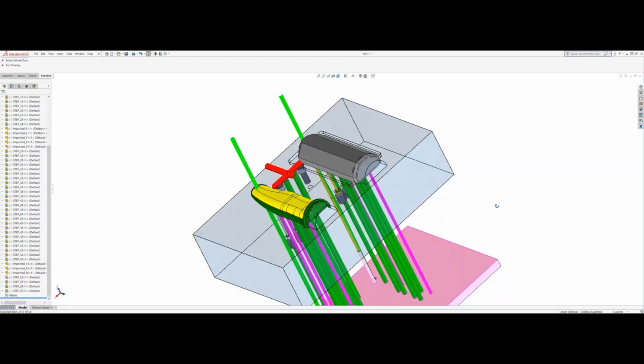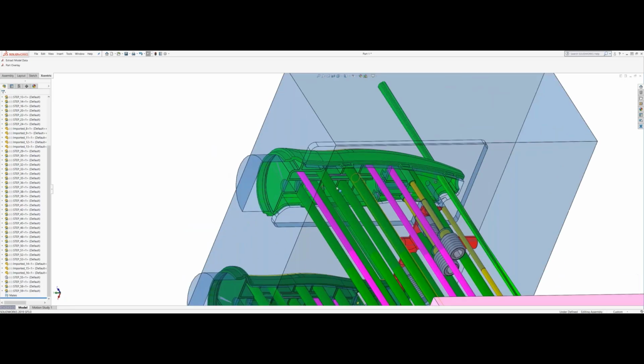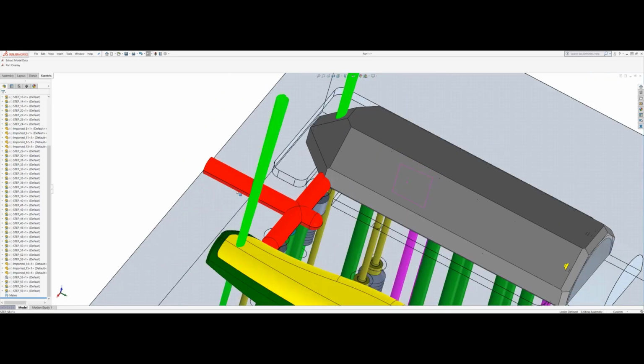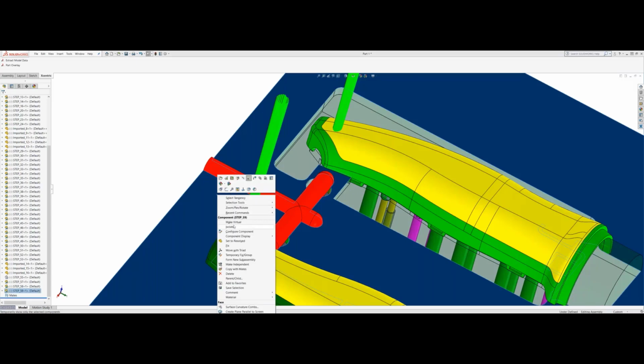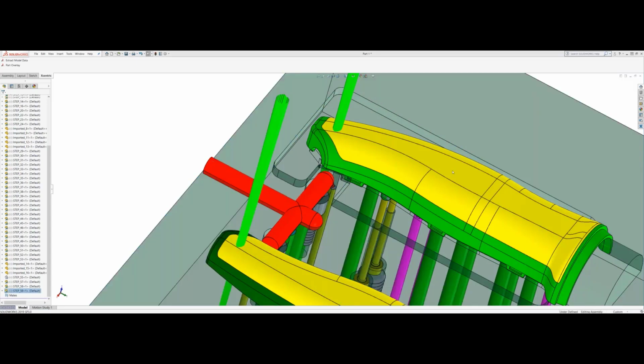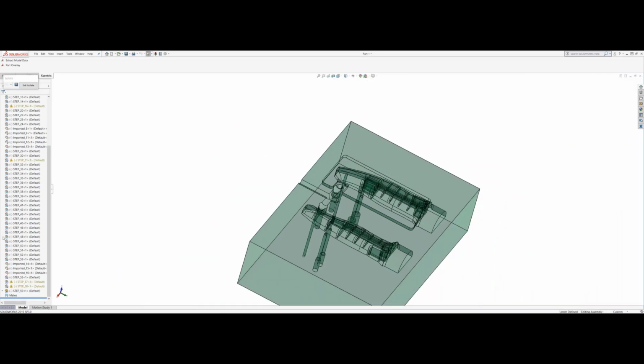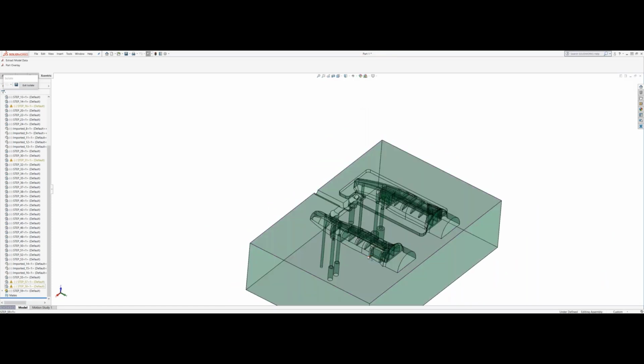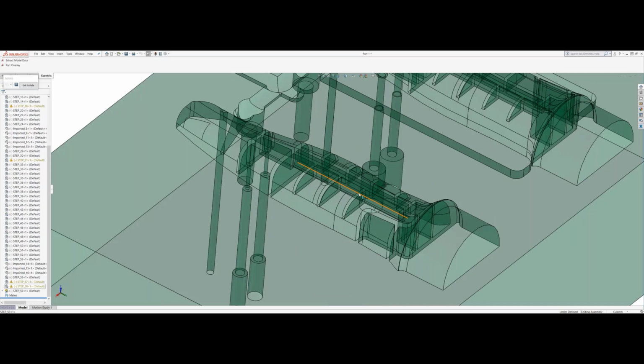Now, whether they add a little pad there or it just simply shuts off on the curvature of the inside surface, that's how we get that to shut off in there. So yeah, it was just basically a copy of the core side of the part, and just shut off on the inside.